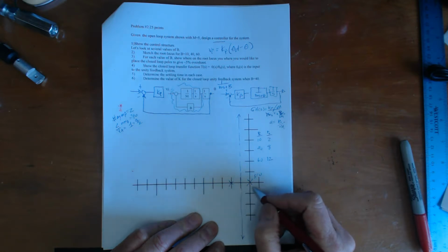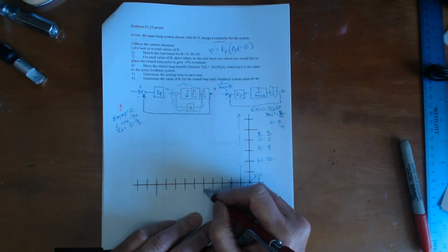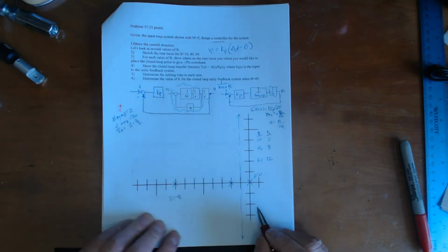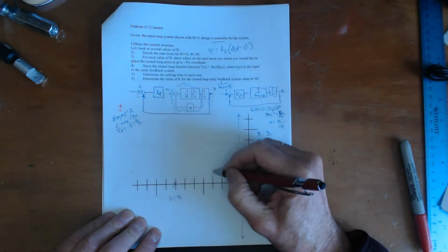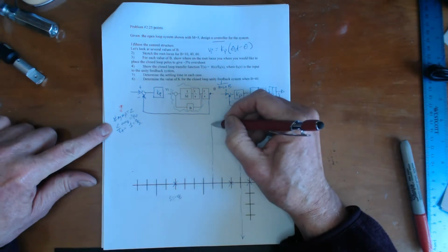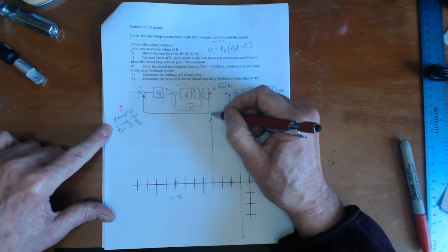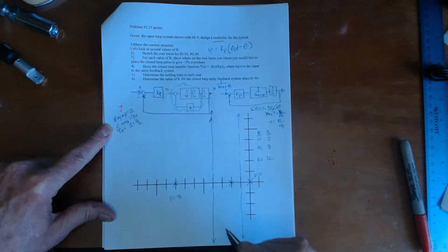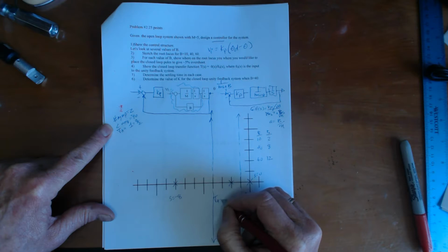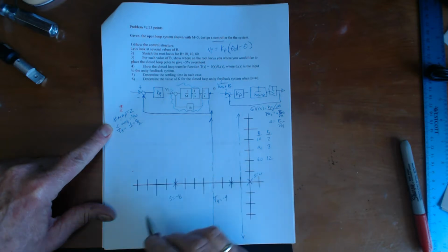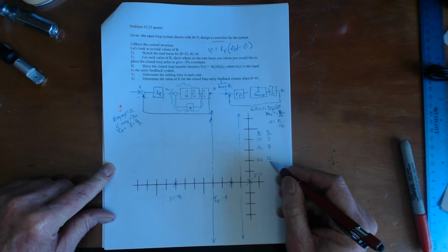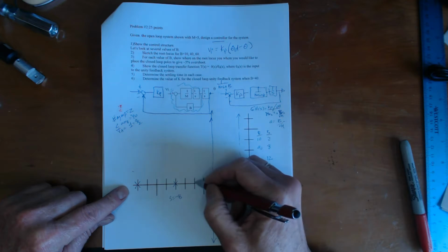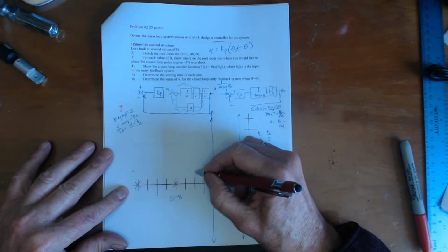then it's going to be s equals minus 8. So that's 5, 6, 7, 8. And again, all of these things still apply. Now what we're looking at is 90 degree asymptotes at plus or minus, with sigma A equals minus 4. And then again for b equals 12, 10, 11, 12. Hey, look at that. I gave you the right number. I can also look at these asymptotes that are going to be at sigma A equals minus 6.